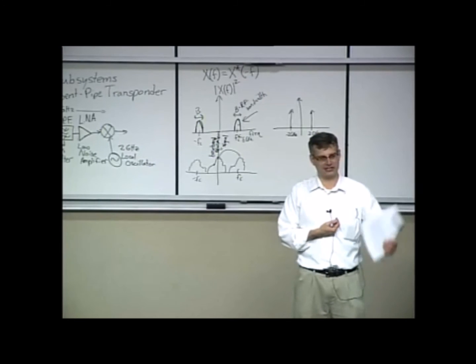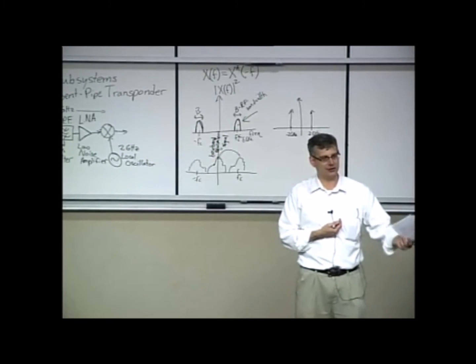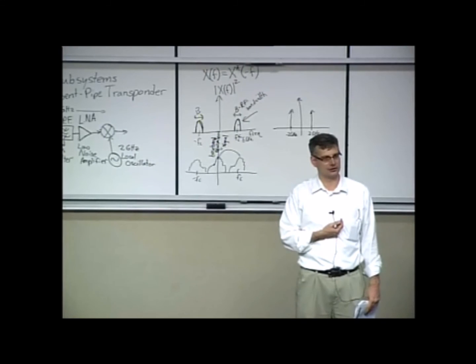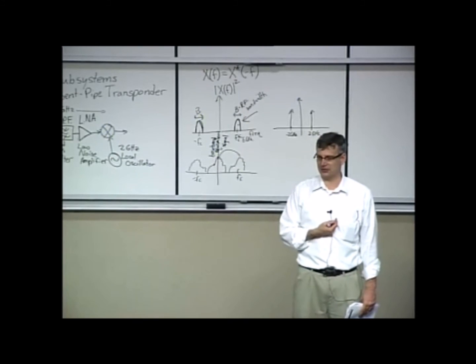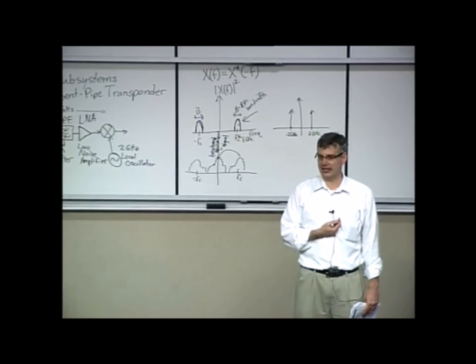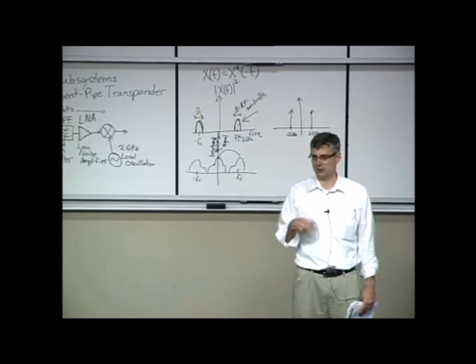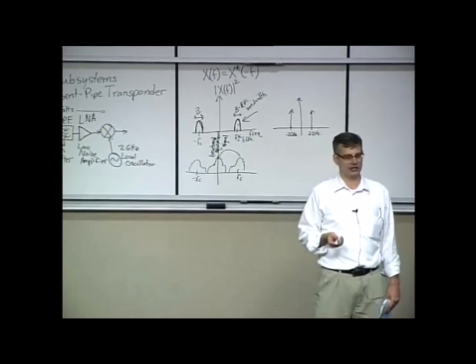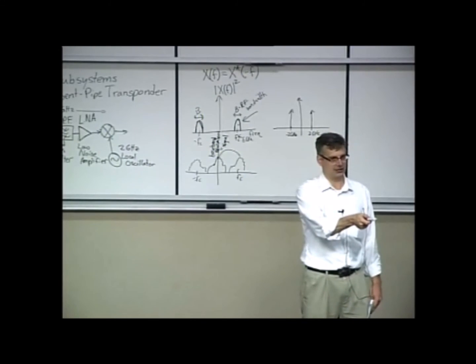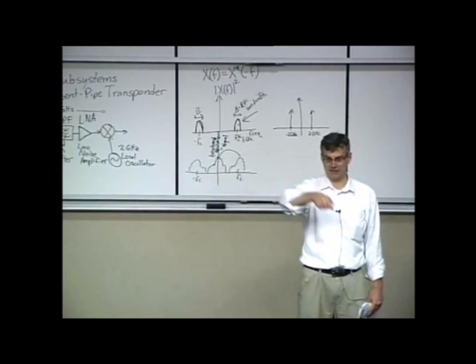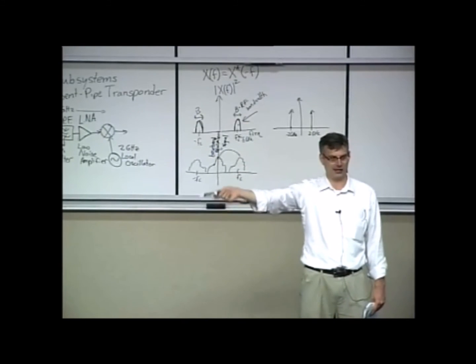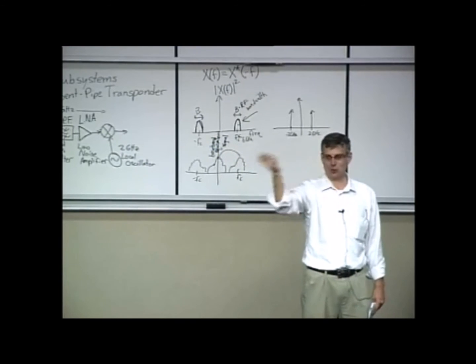And you don't know how many countless hours that has saved you and me during the course of our engineering careers for a linear system. Very useful theorem. There's another really interesting property of the Fourier transform. It's the idea of duality: the idea that what works in the time domain also works in the frequency domain and vice versa. So if convolution in the time domain is multiplication in the frequency domain, multiplication in the time domain is really what in the frequency domain?